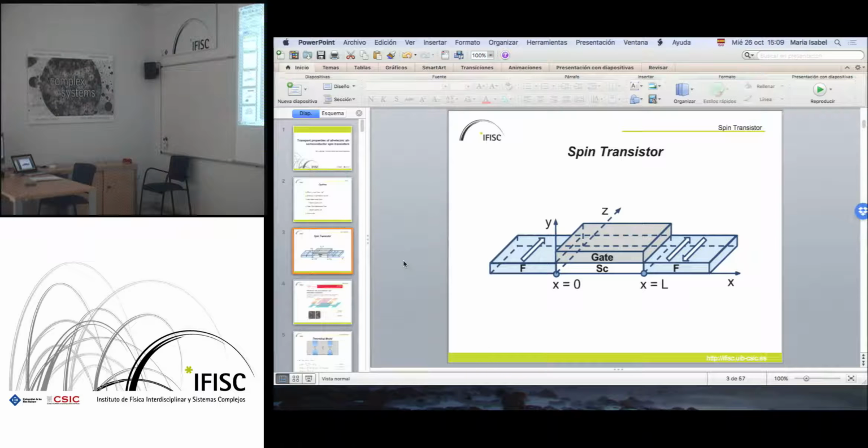But then you show that if the point contact is absent, then you have a nice polarized current, as far as I understand. When you remove the QPCs, we don't have a spin transistor, because we only have a cavity with a Rashba spin-orbit coupling in the central region.